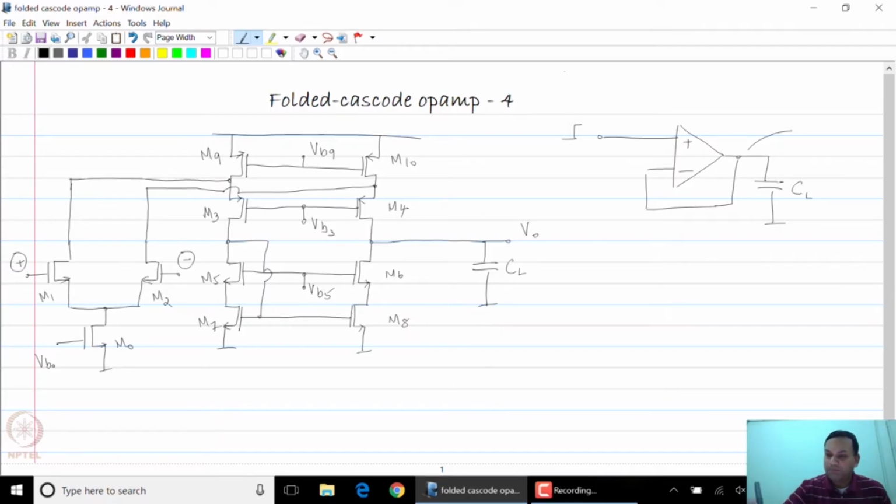When the input step gets really large, the output current of the op-amp cannot support such a large rise time, and there is some maximum output current that the op-amp can deliver.